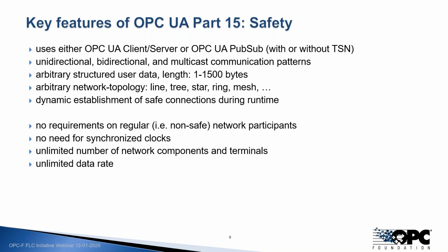Also, synchronized clocks are not needed to implement OPC UA safety. So this is, I think, a good feature. And the number of network components, I'm talking now about switches, routers, and things like that, and terminals, so the participants in the network, and also the data rate are not limited, at least from an OPC UA safety point of view.